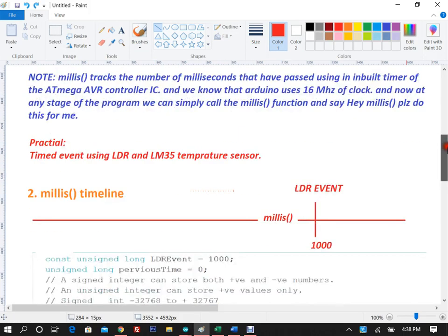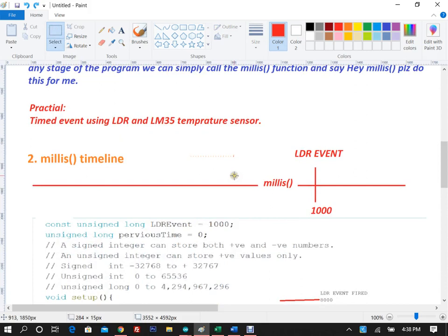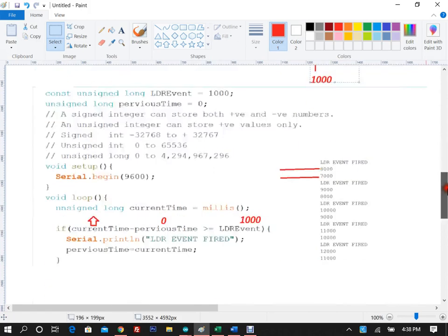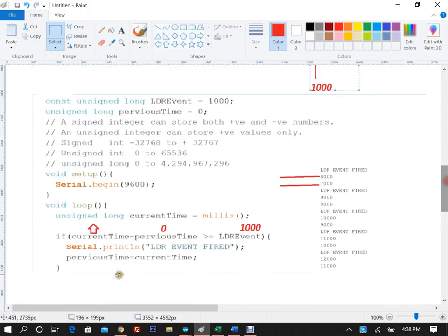All right. And what is the Millis timeline? We have to make sure that we are following the Millis timeline. As soon as it reaches the timeline, we have to distance the timeline so that the repetitive event happens. So how do you distance? We distance by giving previous time the current value after every single loop, so that it's repetitive, right?